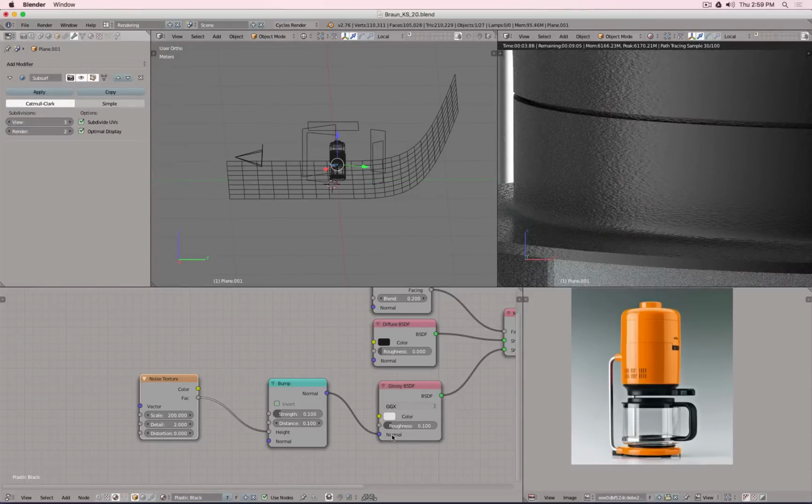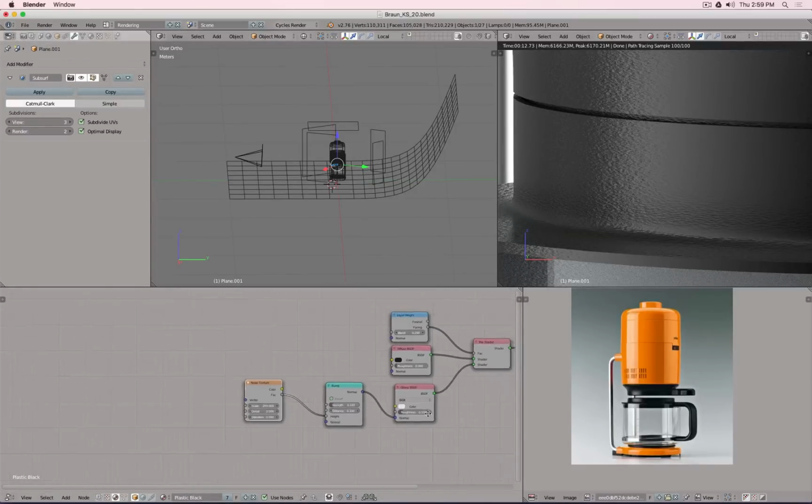So if you ask yourself what is normal, think about normal as a direction. So we use this noise texture to create highlights and shadows going into the surface and going away from the surface by using the normal, because the surface bends into different directions, so all of these highlights and shadows have to flow in the direction of the surface. But there is a little issue. You see the texture seems to be stretched and compressed there, so not really ideal.